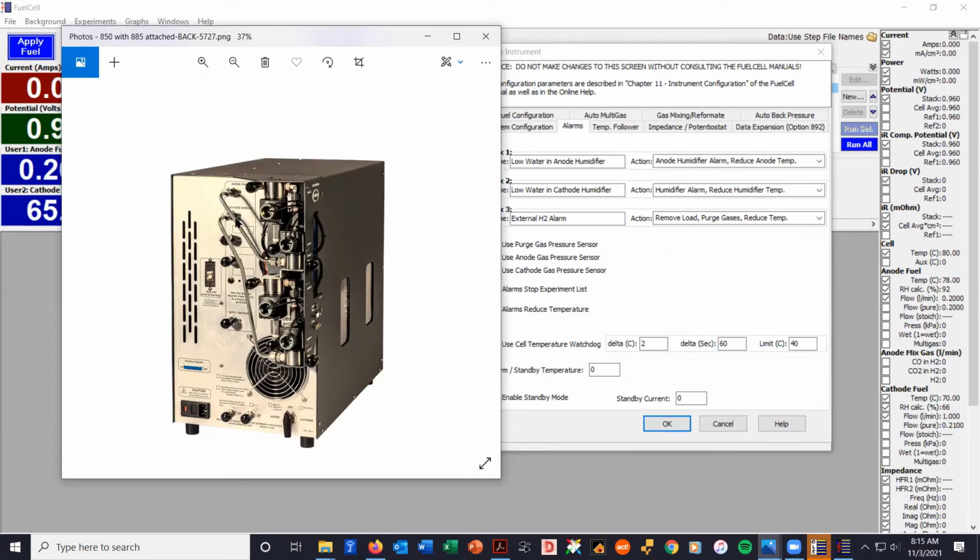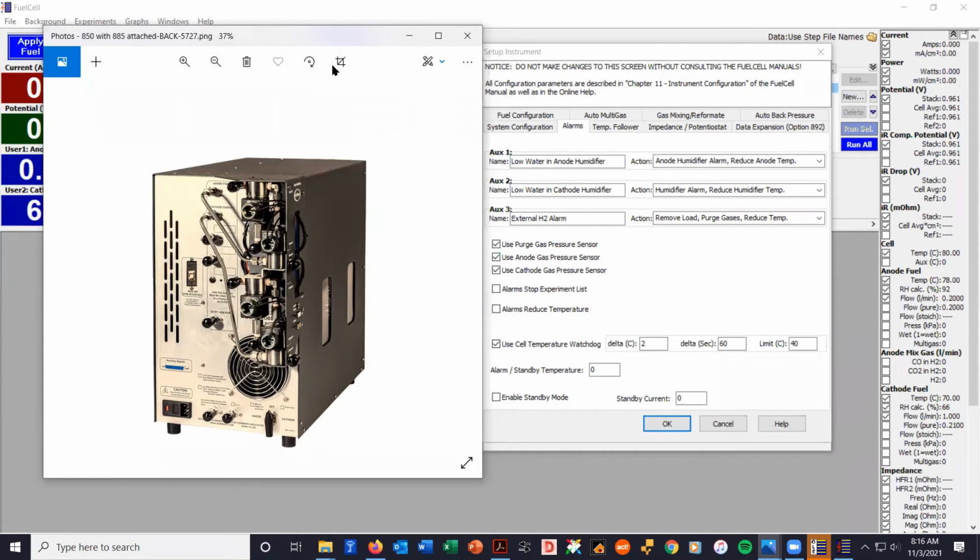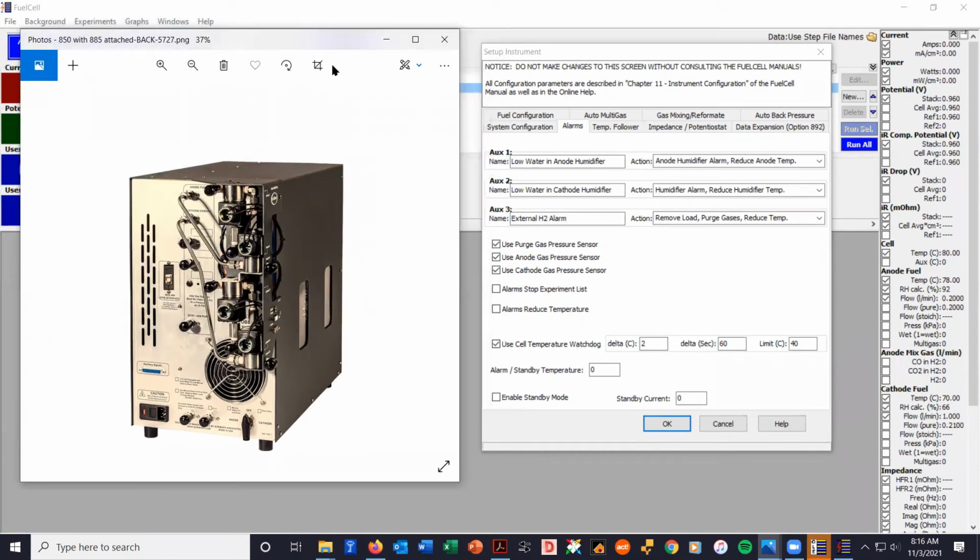So our main hydrogen and air, for example, and then we've got a purge gas. Just beyond this back panel is a pressure sensor, and it's set to trigger at around 3 bar, 45 PSI for those familiar with American or imperial units. So about 3 bar. If the gas pressure falls below that value, then that's typically not a good thing.